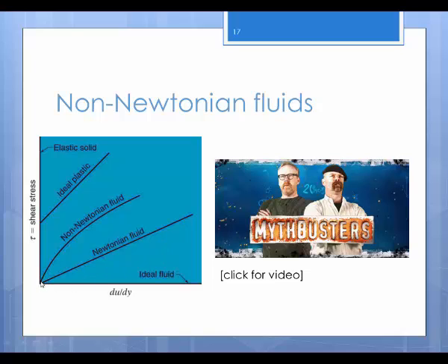In this particular case, as you notice here, the slope is greater here, so the viscosity is larger here than here where the slope is lower. So here the absolute viscosity is actually higher than it is here, which means that as you shear the fluid more, as you work harder to move the fluid on this upper region, your viscosity decreases. We call that a shear thinning fluid.